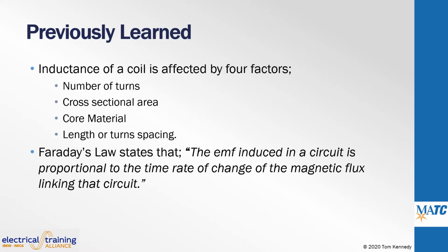Inductance of a coil is related to four physical factors: the number of turns, the cross-sectional area of the core, permeability, and the turn spacing or length of the coil. Faraday's law states, the EMF induced in a circuit is proportional to the time rate of change of the magnetic flux linking that circuit.